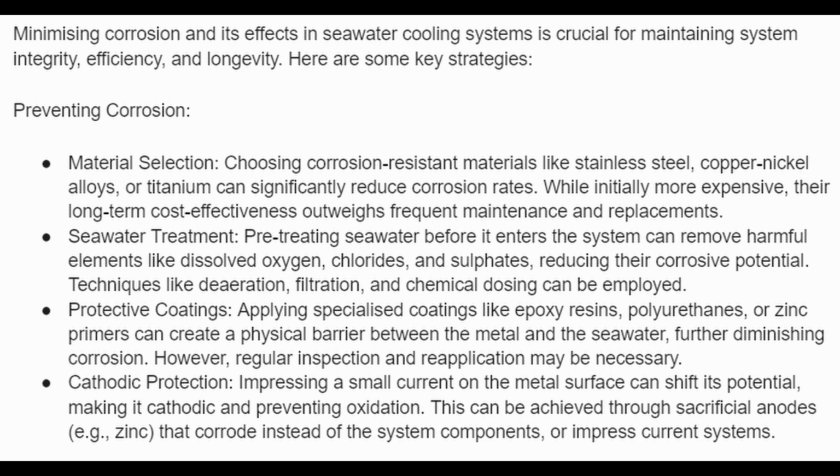Preventing corrosion by material selection. Choosing corrosion-resistant materials like stainless steel, copper-nickel alloys, or titanium can significantly reduce corrosion rates. While initially more expensive, their long-term cost-effectiveness outweighs frequent maintenance and replacements.